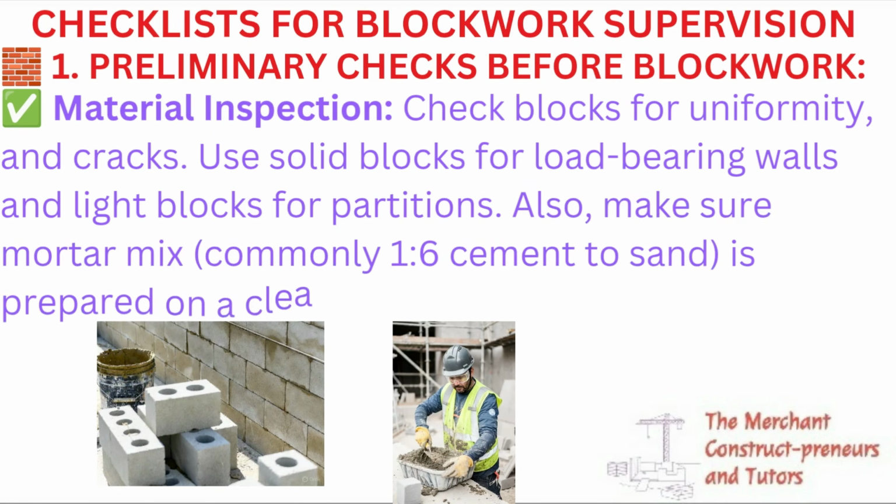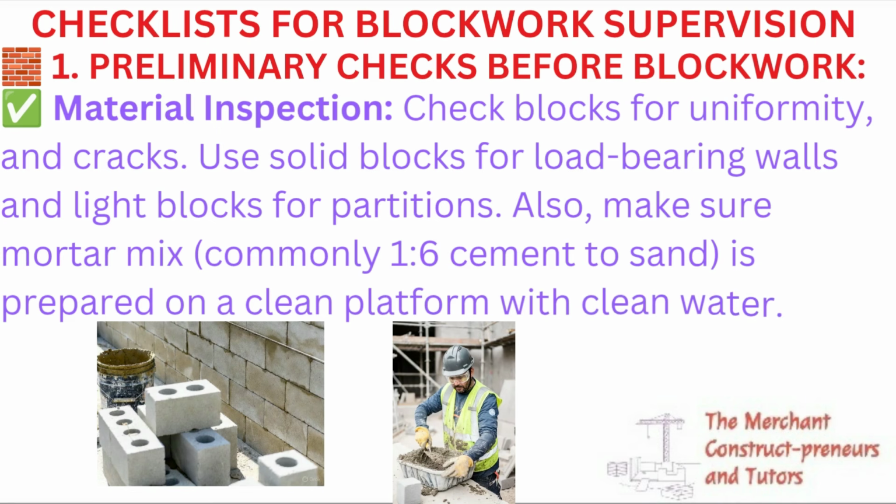The checklist for block supervision. Number one thing you're going to do is preliminary checks before block work. Before even doing anything, you need to check certain things. So the first thing you need to check is the block. Am I using the correct size of block? Is the block okay? Is it uniform? Is it square? Do you want to use solid blocks or hollow blocks? What do you want to use it for? Partitioning, load bearing walls, and then even the mortar you want to use.